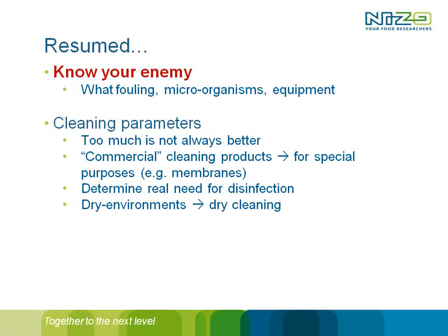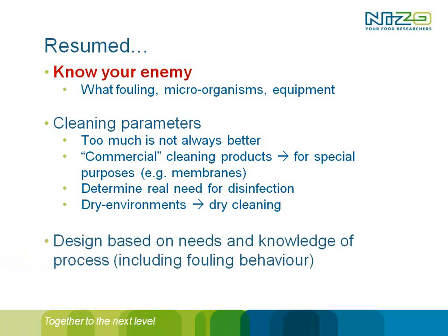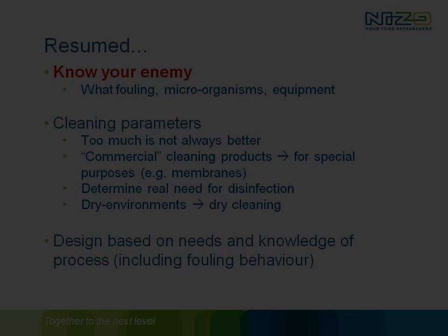And in dry environments, try to do a dry cleaning and try to avoid wet cleaning as much as possible. Your design should be based on needs and knowledge of the process. So think about your fouling behavior while designing a process, and don't do it afterwards when you build your plant and you're trying to solve the problems, since changing an existing configuration usually takes much more effort than doing it in advance.